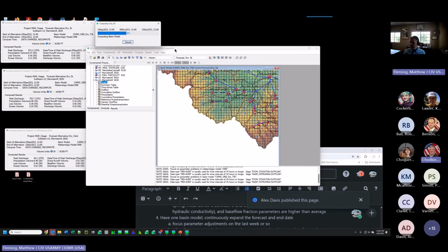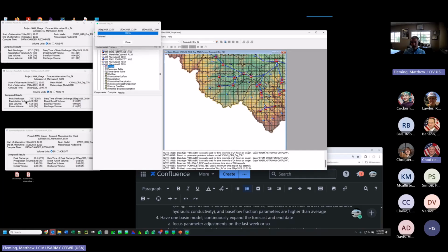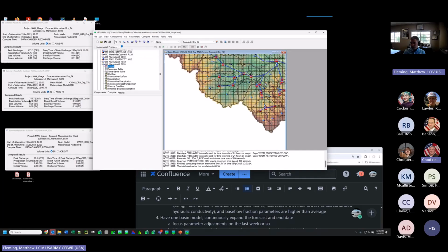Yep, it's going to be around the 20-second mark. So what I'm getting to is even though there's some noticeable difference between these two methods, the 2K and the 5K grid cell size, you do make up for it in runtime. And even though the differences are there, you would still have a chance to modify the parameters in that model. So you can still get accurate results. It's just you're going to get to those accurate results faster with a shorter runtime.